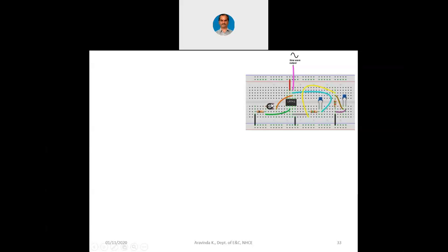Actually, its resistance is a complete circular or semicircular track there. On the semicircular track, the wiper is going to move. It is a minute wiper or a miniature wiper. And the wiper can be moved by rotating a screw at the top by means of a screwdriver. So this is called a small potentiometer or preset. And you have other resistors and capacitors.